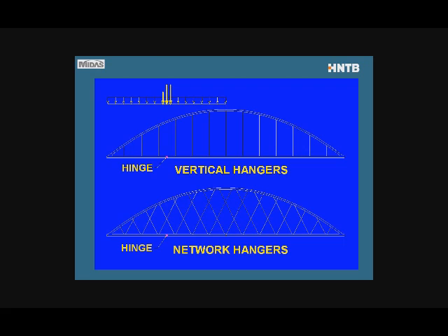Network tied arches, the tie is fracture critical. That means if we lose the complete tie, we lose the bridge. So the tie is crucial to sustaining the load. You can imagine the arch wants to spread out under the weight, and then the tie holds it together, but with no tie, the arch will just collapse. Now, what I'm interested in here in this comparison is what happens if the tie is only partially ineffective, say a plate has fractured or something. And so we still have the axial load capacity, but we don't have the bending capacity.